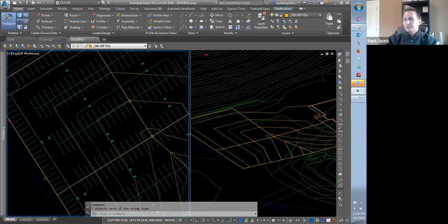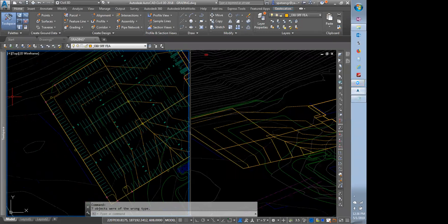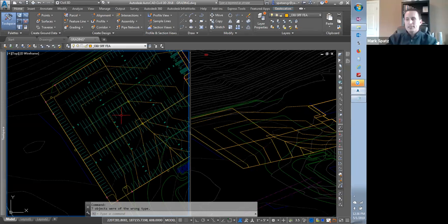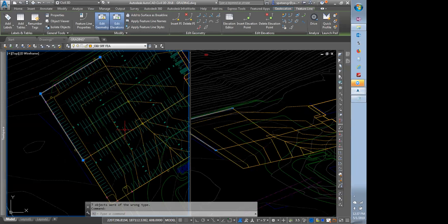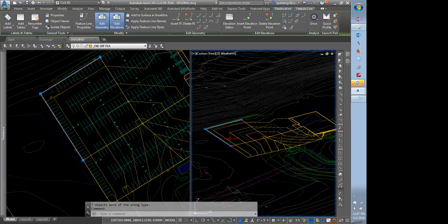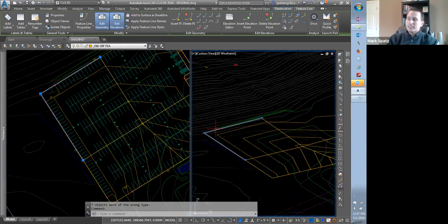Do you get a surface that shows the stuff? Mine isn't quite like yours, yours are almost square. Mine are kind of going diagonal. Yeah, it depends if you have this stuff drawn. Like if you didn't get this drawn in. I do. Yeah, I'm not sure why I did that. That's just a matter of what break lines you have and don't have.